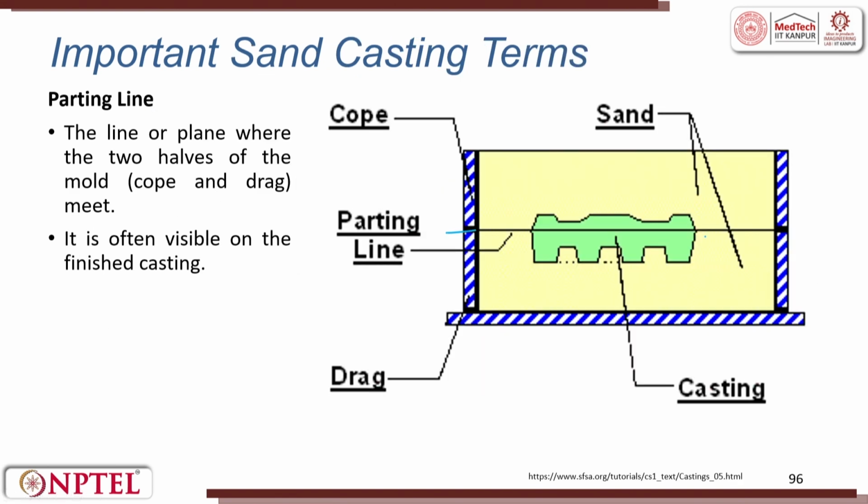Parting line, we have seen the parting line. One of the toughest and most difficult tasks is identifying the parting line for any given component. The parting line dictates the mechanical behavior. So, you can make the component like this, like this, like this. These are all parting lines. It is left to you to decide.